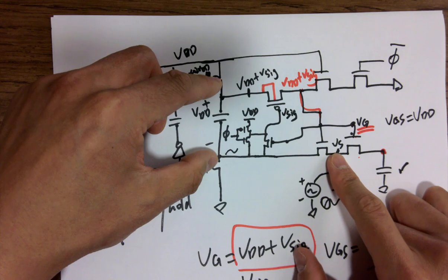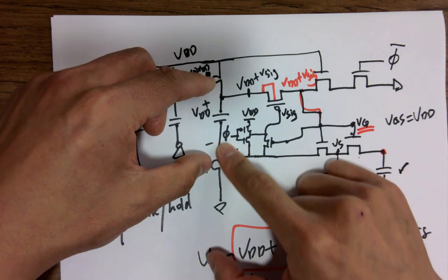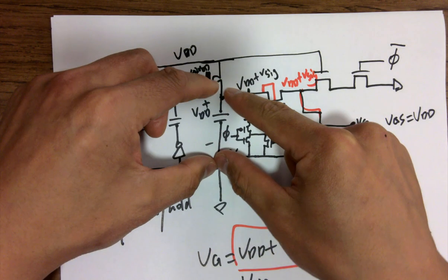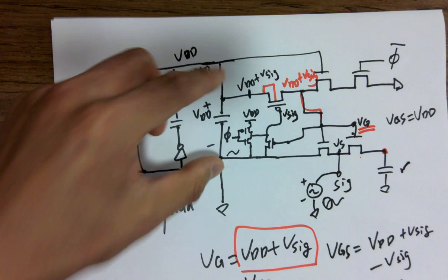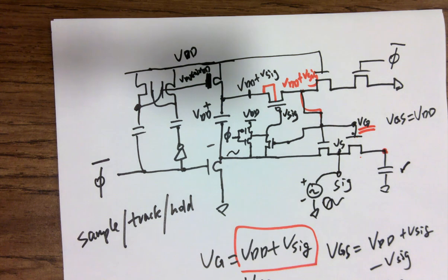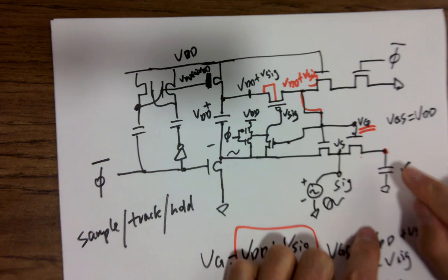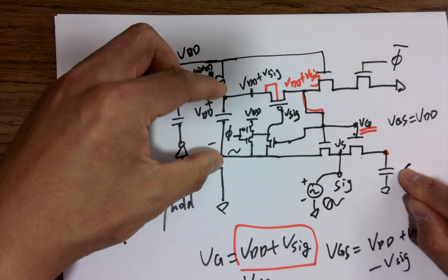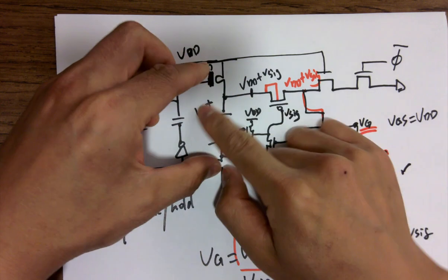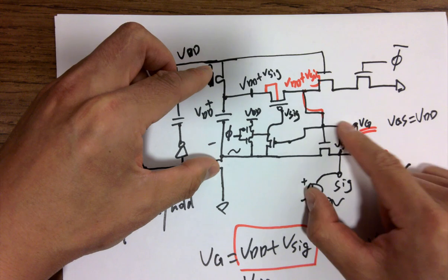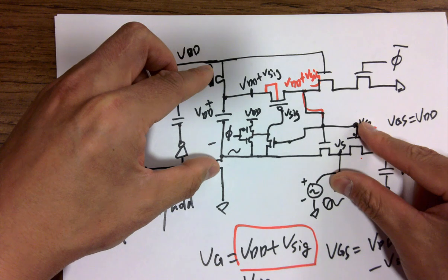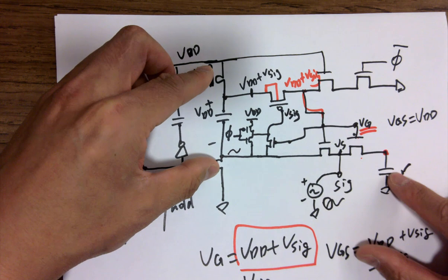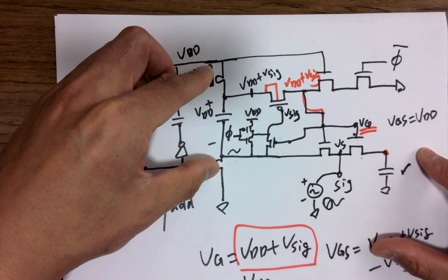And whenever this is going up, it passes through these transistors and adds to this VDD, so it's bumping the VDD up as well. So the VDD is not a floating VDD, it's adding that signal to the VDD. And this one passes through all the transistors and reaches this one and forms a constant VDD, so it's not getting distorted, and it's nicely tracking it. Okay?